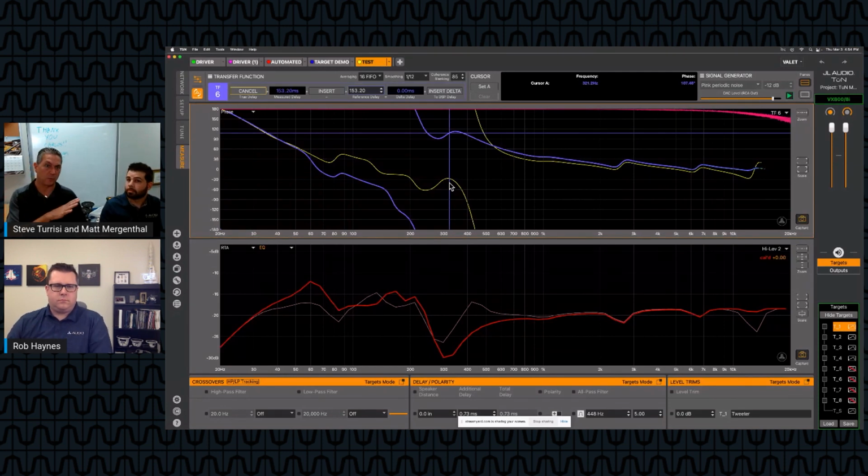So one thing that we didn't really talk much about was the electrical input capability on a Max box, on these XLR inputs that we're using to take these measurements. It's 80 volts peak. Not peak to peak, 80 volts peak. So it would be 160 volts peak to peak. We did this because we wanted you guys to be able to measure the output of virtually any amplifier that you're likely to encounter for almost any application that you're probably ever going to see.